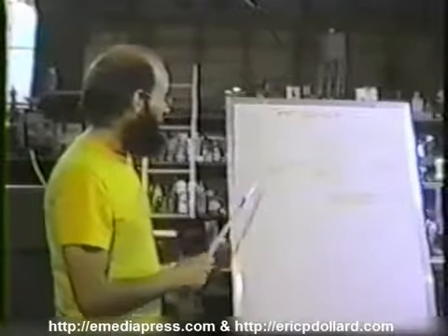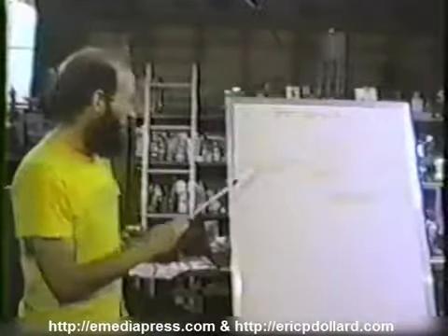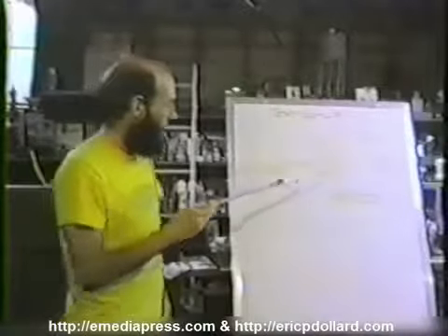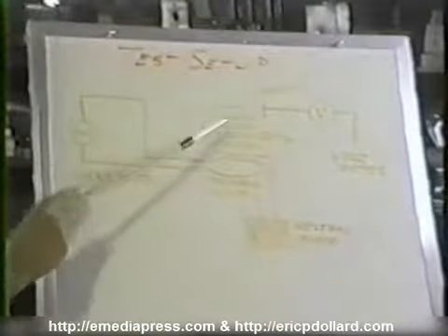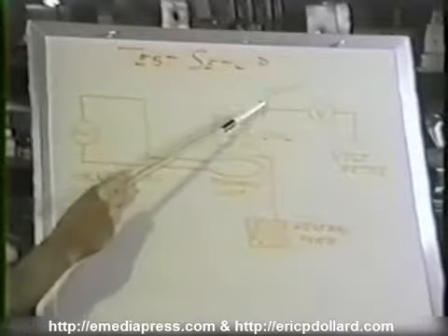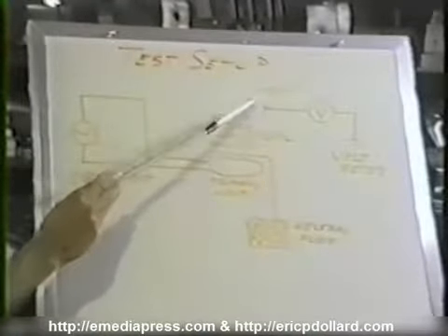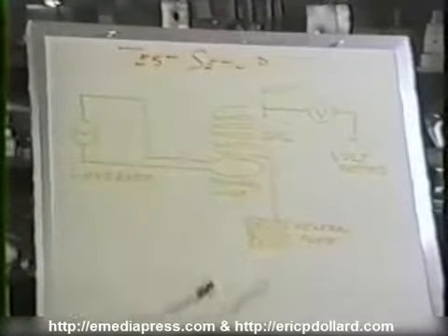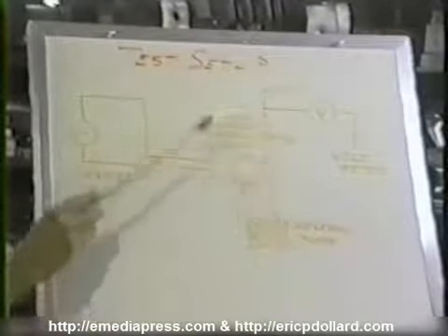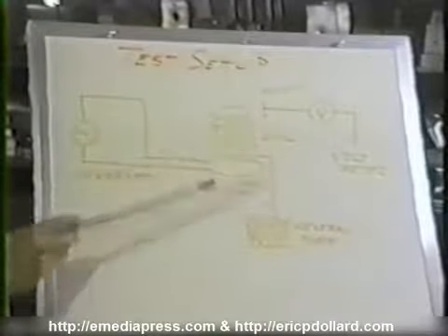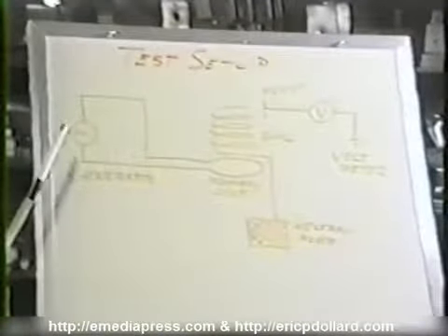Okay, now we have our longitudinal wave test setup. Again, we have the same generator. This time our transformer couples the generator energy to the first turn of the coil, which is wound of fairly fine wire. And then we have a capacitive probe pickup to measure the voltage rise at the end of this coil. And at the neutral end of the coil, we have a large capacitance plate to produce our impedance dissimilarities, so we end up with a quarter wavelength rather than a half wavelength resonance on this coil.